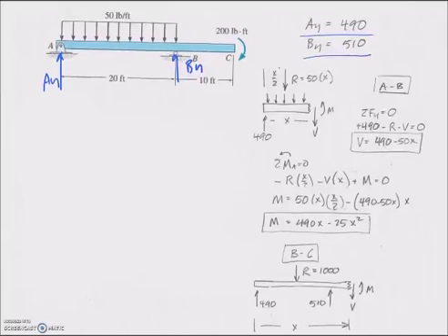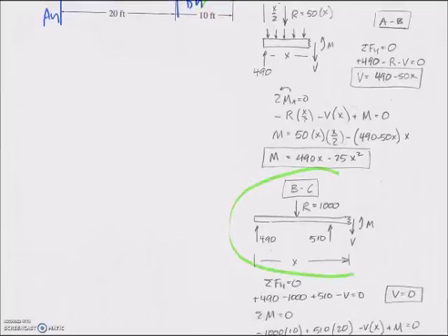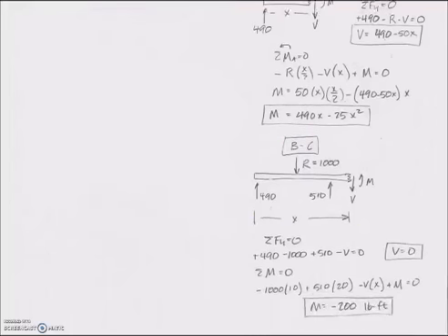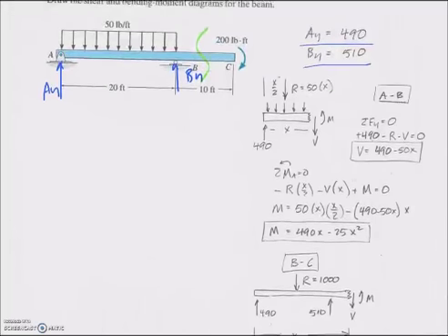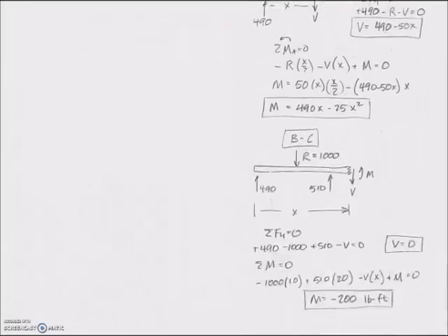But now let's look at the shear and moment equations for this section out here. Again, draw the free body diagram for that section right there and write the equations. Sum of forces in the y, and it turns out that shear is equal to 0 out there. And then moment looks like it is constant. Let's look carefully again at what's going on out here. There aren't any applied forces, so the shear is 0 and doesn't change out there. And the constant moment is counteracted by that couple at the end. Again, we'll talk a little bit more about that on Wednesday. But here are the valid shear and moment equations for those two sections.